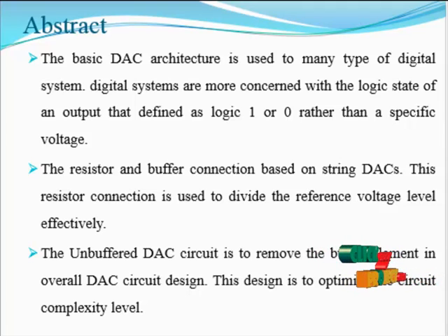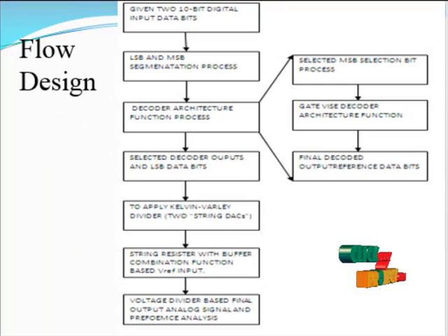The DAC occupies most of the data driver IC's chip area and determines the cost of the ICs. For the DAC resolution, a small area high resolution DAC is required. It realizes high color depth and lower cost amplifiers. Now we are going to discuss our product flow diagram.